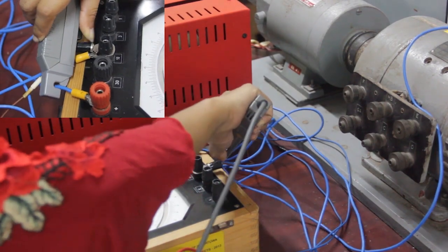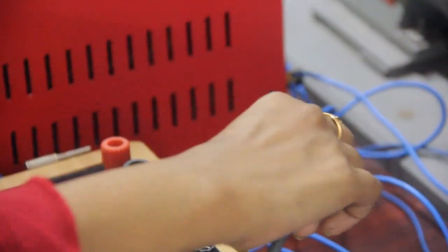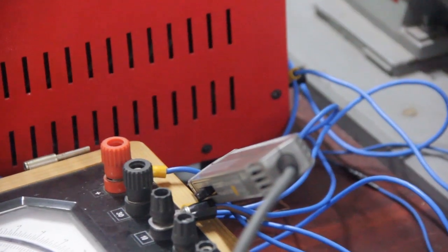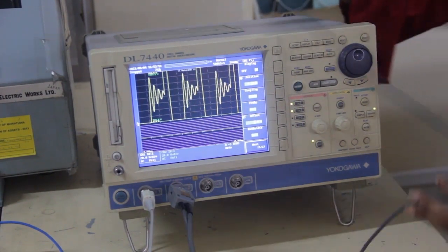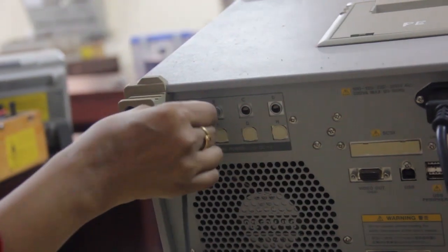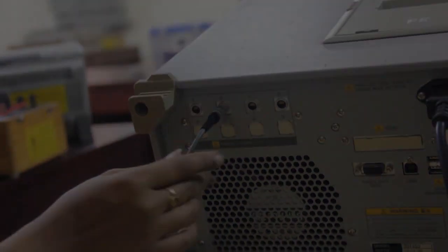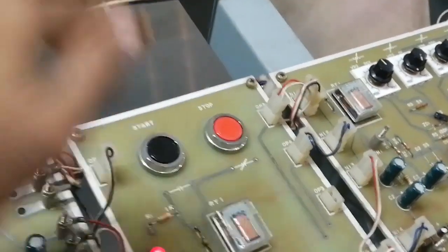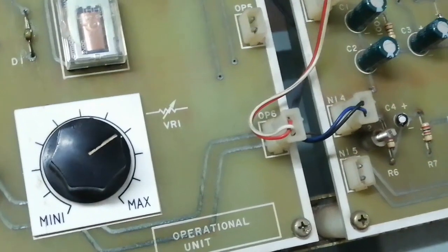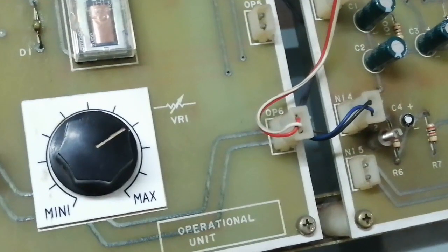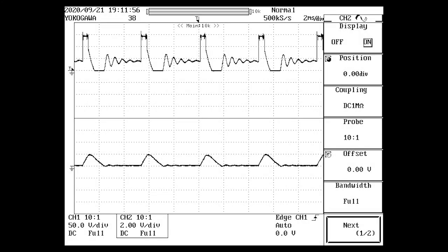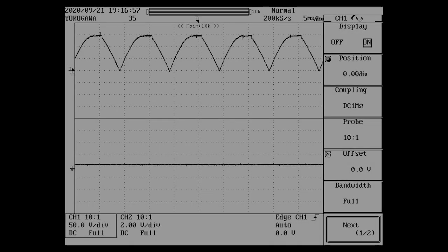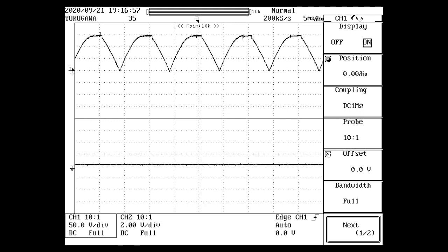We have to connect the oscilloscope CTs as well for this part. The CT is connected to one of the cables on the ammeter and the other side is connected to the oscilloscope as shown. After switching on the chopper, we set the speed input potentiometer to step 7. Then we obtain a couple of plots. First, the armature voltage and current waveforms. Then, field voltage and current waveforms.